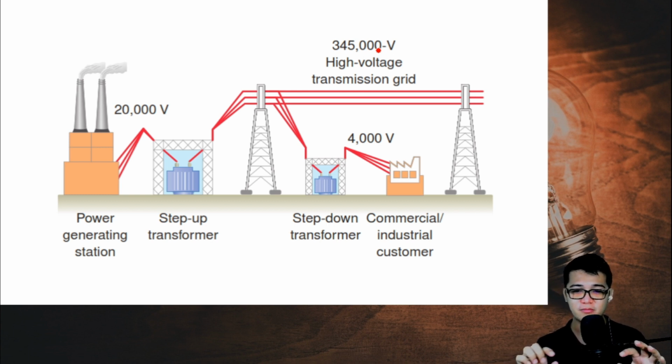Because class, as we transmit this electricity, while the electricity passes through these transmission lines, okay, there are actually losses. And you can see that in your electric bill. We call that the transmission losses. Since these lines, these cables, have resistance. We know that when there is resistance, there is power dissipation. Okay? I squared R. Okay? The square of the current times the resistance, that is our power loss. And because the current is squared, the larger the current, the larger the square, okay? The more power we will lose.